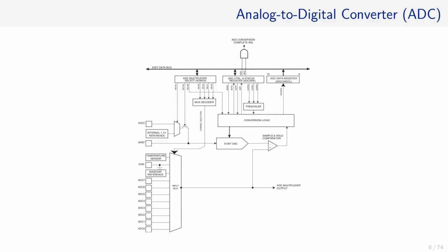And for that, the ATmega is equipped with an analog to digital converter, which does exactly what we just did, but automatically and a lot faster. Let's talk about how the ATmega converts an analog value into its digital representation so that you, as a developer, can make the right choices and use it in your program. In the world of Arduino, it is simply a function call to analog read. However, it is a bit more complicated than that.